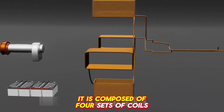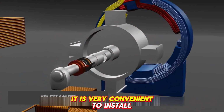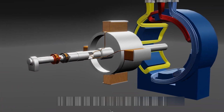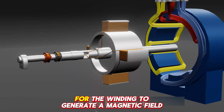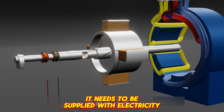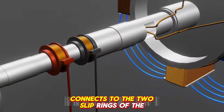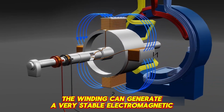It is composed of 4 sets of coils. Since the electromagnet is not powered on at first, it is very convenient to install. All you need to do is take the 4 sets of coils and wind them separately onto the 4 protruding magnetic poles, and that's it. This combination of coils is also known as the excitation winding. For the winding to generate a magnetic field, it needs to be supplied with electricity. Therefore, there is also a DC power source here. The DC power source, through 2 wires, connects to the 2 slip rings of the rotor. This way, the winding can generate a very stable electromagnetic field.